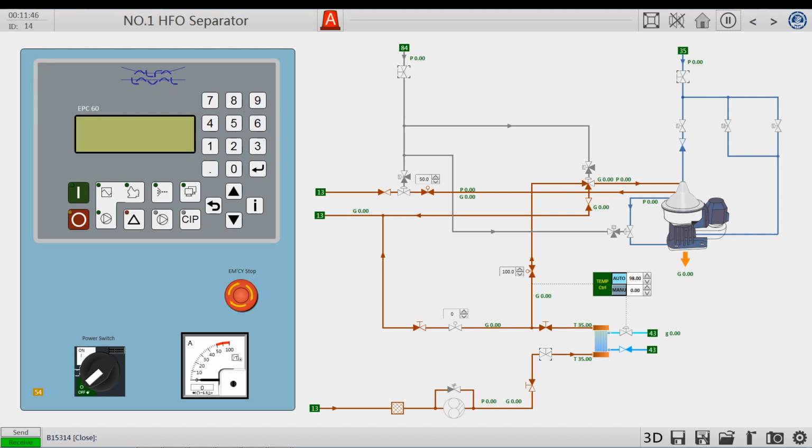Before preparing the purifier system to start, the 3 fuel lines need to be connected to the tanks. All valves should be opened correctly. We need to confirm the fuel source tank and the destination purified fuel oil tank. When handling fuel transport operations, special attention should be paid to proper piping and valves to avoid incorrect operations.